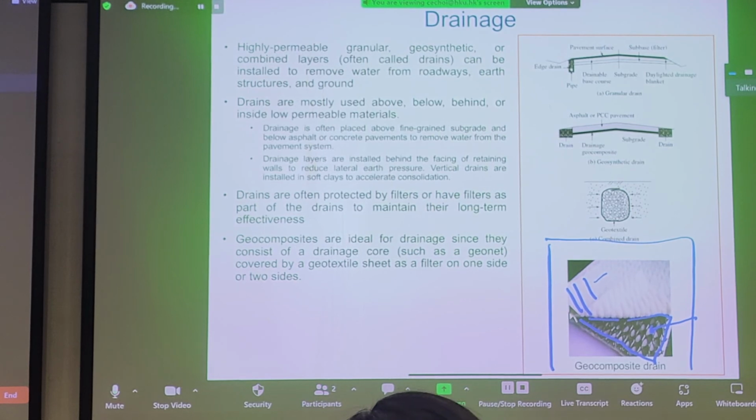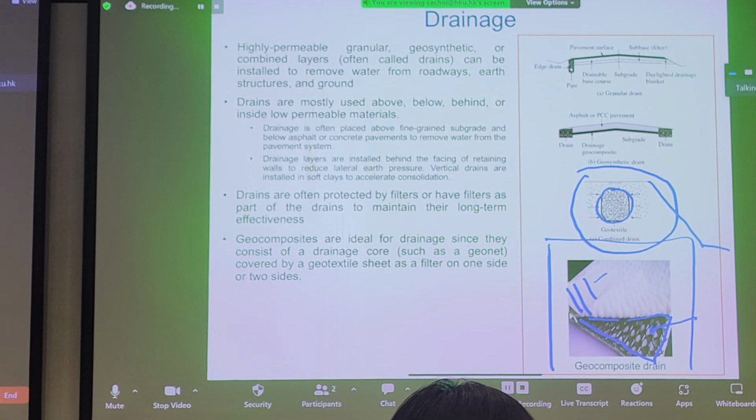As we mentioned, if you look at this example here, you can actually make a drain without a pipe. You can just take coarse gravel material, wrap it in some geotextile, and it can function as a pipe or a drain layer. This can be placed on the top of a slope to minimize infiltration into the slope, for instance. So for drainage, anything that promotes the movement of water through it. So we don't want anything impervious. And as I mentioned, geocomposite geosynthetics are perhaps the best.